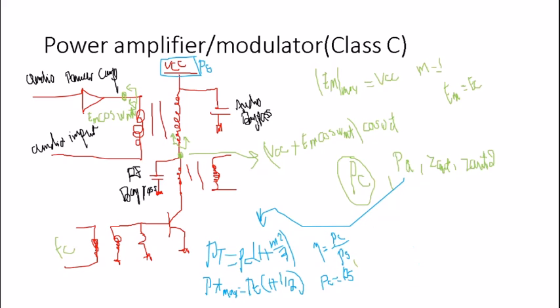So taking all that into consideration, we can come to the conclusion that the power coming out of this audio power amplifier, P_A, obviously at maximum because we took that total power at maximum, equals 0.5 multiplied by the power of the carrier, or 0.5 multiplied by the power of the source. So now we've found an expression for the power at the output of the amplifier.